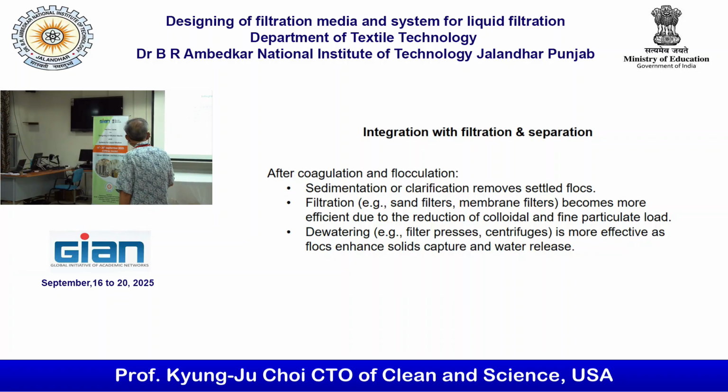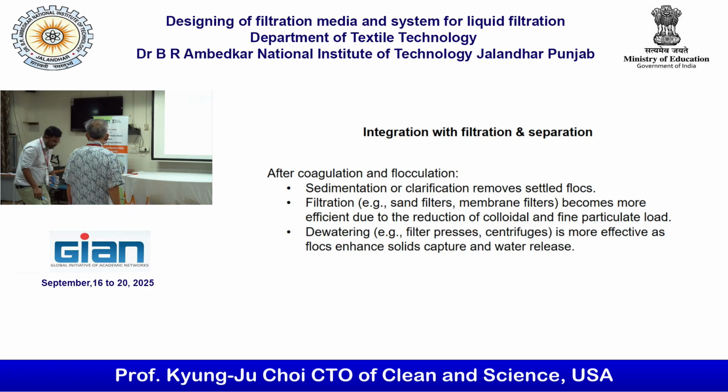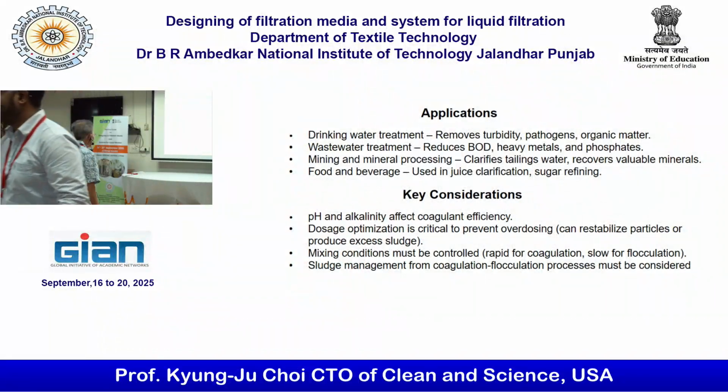Anyway, after coagulation, flocculation, sedimentation, classification, filtration, and dewatering. The applications: drinking water treatment, wastewater, mining, mineral processing, and for the beverage. The key consideration, pH, is quite important. The dosage optimization is critical to prevent overdosing. The mixing condition must be controlled.